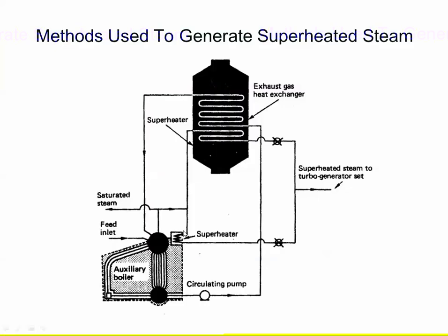Now, right here, what's going on is they've moved the superheater. Instead of where we saw it before, they've moved it up instead of the economizer. This is going to drop the efficiency of your plant. The reason they don't do that is they are so worried that untrained engineers could burn up the superheater if it's down here, because it's exposed to the highest temperature gases in the boiler, which are well above the melting point of steel. And down here you can very, very quickly, within 5 minutes, destroy a superheater.